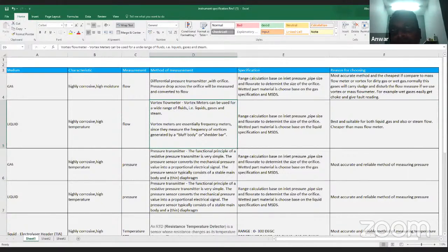This will be formulated into the maintenance module, so the field instrumentation engineer will not forget to do the calibration accordingly. We have frequencies like 3 months, 6 months, and 1 year. Some of the equipment we only calibrate every 2 years or so.